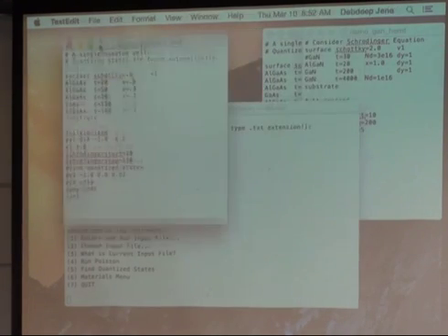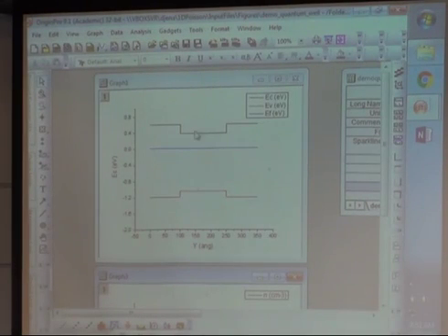in the quantum well, right now there are no charges, so where would I put the dopants, right? That's the first question we need to bother about. So you can obviously put the dopants here in gallium arsenide, and that will ionize and you get the electrons there. But I think you can see generally what will happen is the electrons are in the same place as the ionized donor atoms, and they will scatter off them, and the mobility would be low.